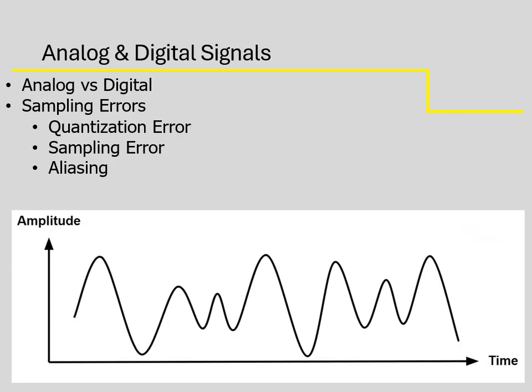A sampling error comes when we are only taking samples at certain time intervals. So here I'm going to exaggerate this. I'm making pretty large time intervals. If this is when we're sampling, for example, see this? We're having some kind of dramatic event happening right here, where the output from the device is going up and then going back down. And if I'm only sampling at these times, I'm completely missing that. Okay, so that's a sampling error due to timing.